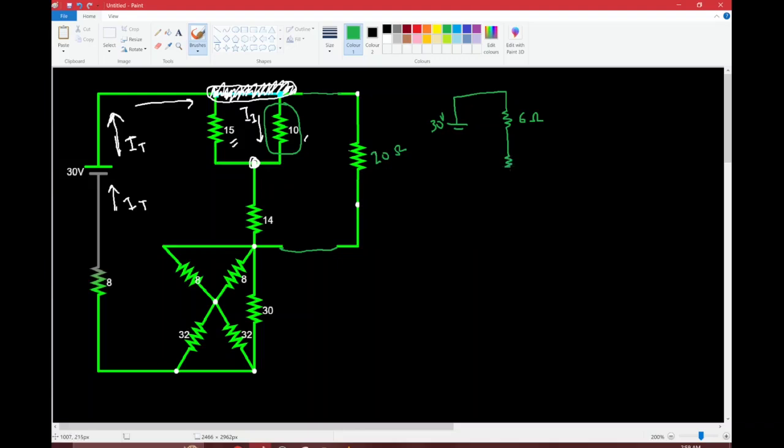Then this one over here is going to be 14 ohms. And I'm only going to draw this circuit up until the point where these two paths come together. So this other path over here is the 20 ohm path, like that, and it comes back together like this. 20 ohms. What I'm going to do is slide these guys together as well, like this. And it was 14 and 6, so that's going to equal 20. All right.